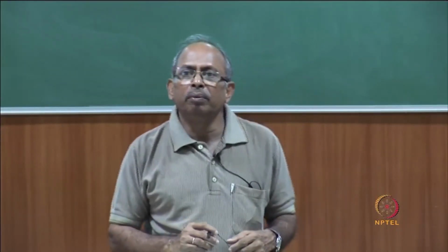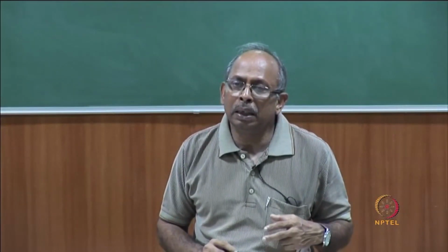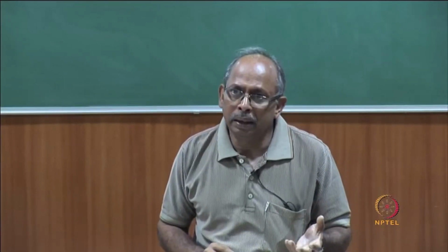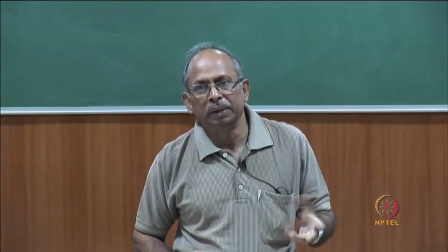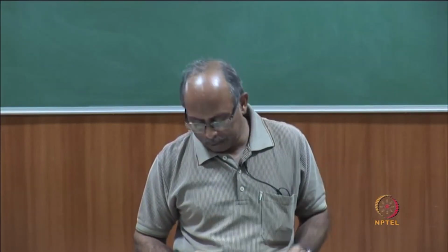So, now let us look at modulus of elasticity in terms of the factors that affect it. First of all, you see here this is for cement paste. This is the stress strain curve of cement paste, this is the stress strain curve of aggregate, which generally would show something like that, and concrete shows a stress strain behavior of this kind. So, aggregate stress strain behavior is of course fixed, because you have taken the rock and the behavior will be fixed.